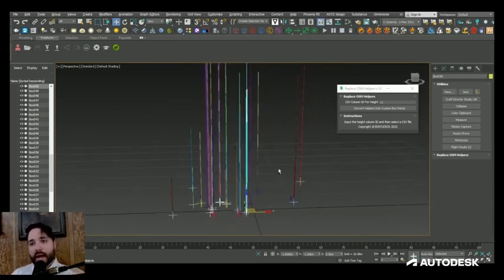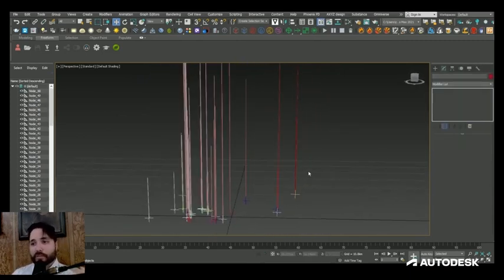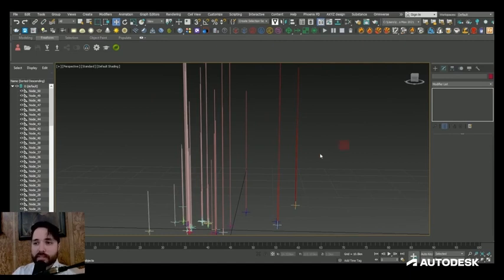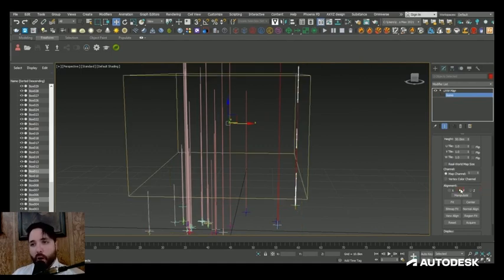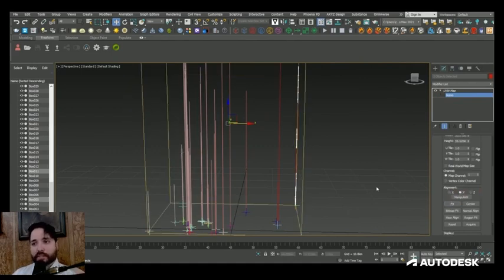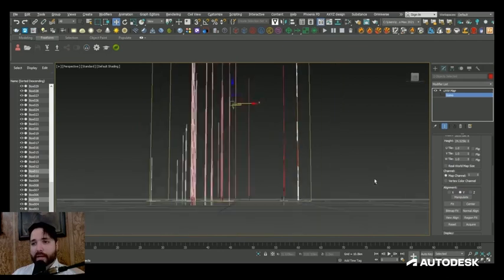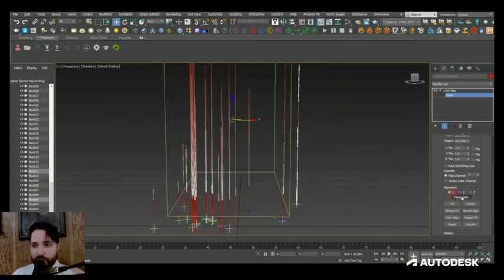Once that was done, I added gradient UV mapping to all my box towers so that I could represent the intensity with the color gradient. By applying a shared UV map and rotating the gizmo, all I had to do was apply the same gradient material to all of my box towers, and everything was then ready to export into Omniverse Create.